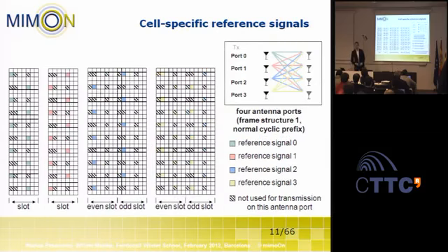Yeah, it's basically fixed. It depends on the cell. Different cells have the pilots at different positions, but it's fixed generally. Which channel estimator? The channel estimator is not specified in the standard. That's of course the choice of the manufacturer. Usually we look at some Wiener filter in time and frequency, but this is not a question of the standard. It's a question of the manufacturer.